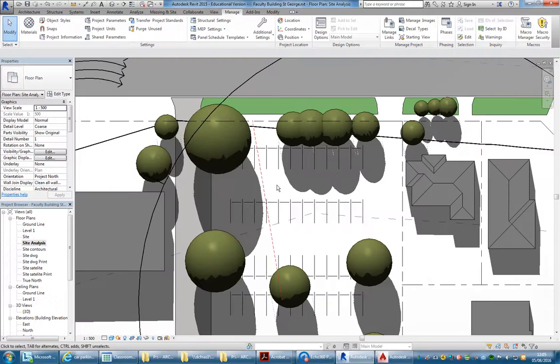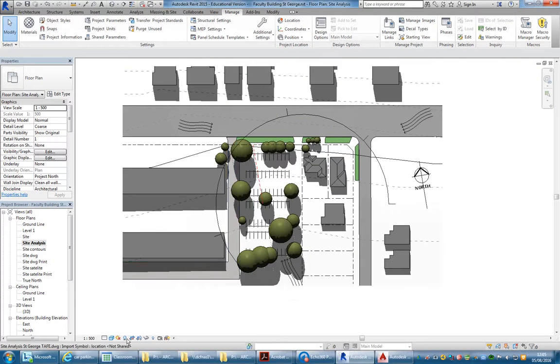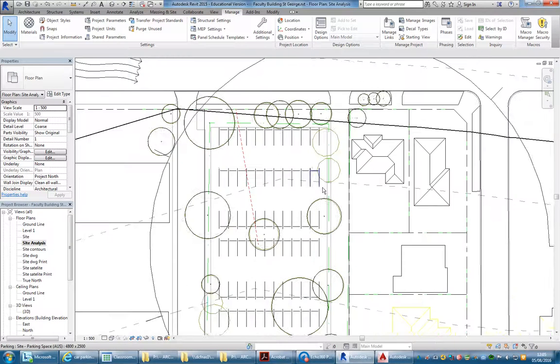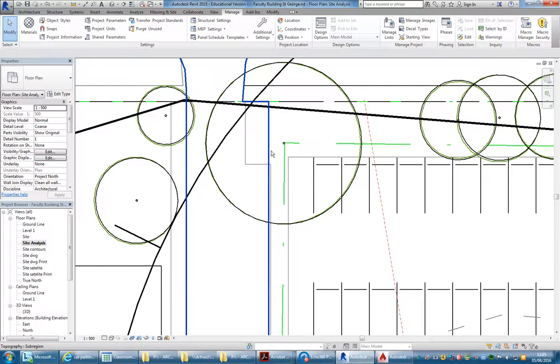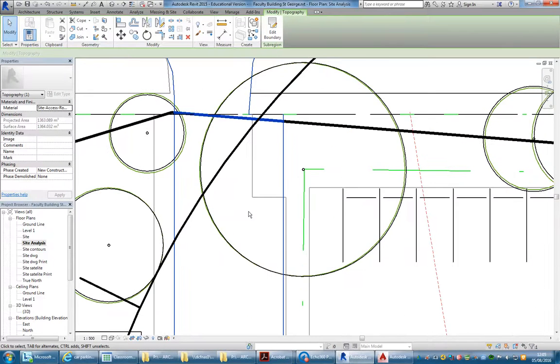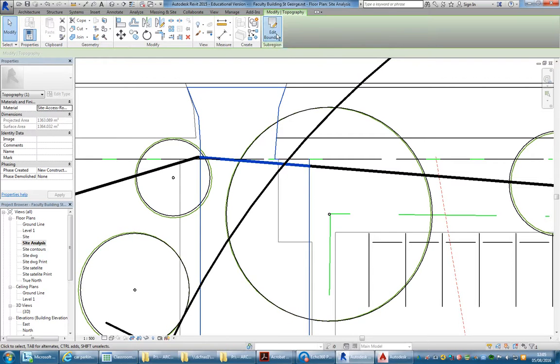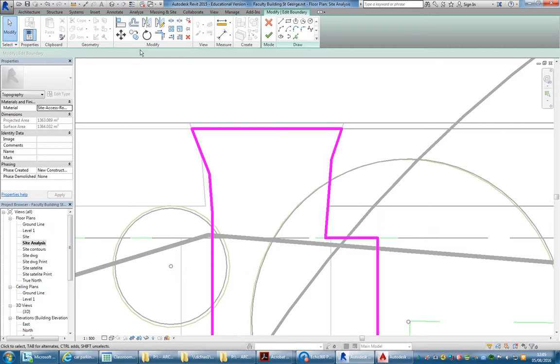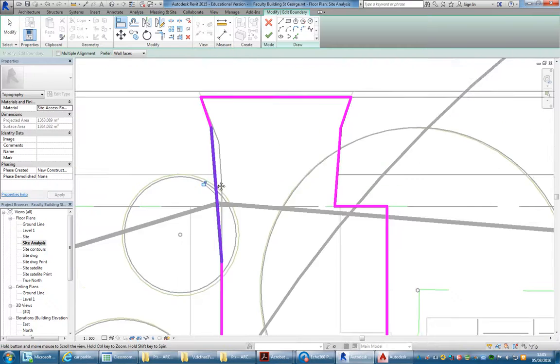Okay. I can't see the drawing there because it's set to shaded, but if I go to wireframe, then you'll see the line work that I've brought in from AutoCAD. So I'll start by adjusting that sub-region that I've drawn already, just in Revit. Going to Edit Boundary, I can use simple tools like Align to pick the line work I've drawn in AutoCAD and line up the lines I've drawn in Revit with that.